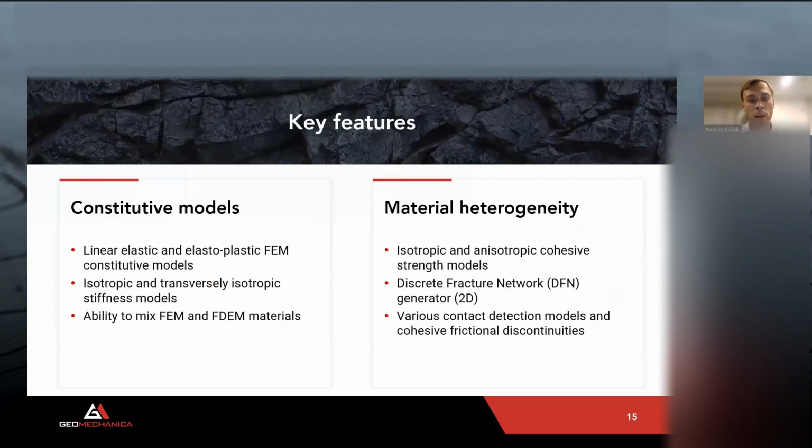Let's look a bit at the key features, and some of these I will talk about in more detail in a few minutes. In terms of constitutive models, at the finite element level, we have linear elasticity, and more recently we have included elastoplasticity. We can incorporate the isotropic as well as a transverse isotropic linear elastic model to capture, for example, the response of bedded materials.